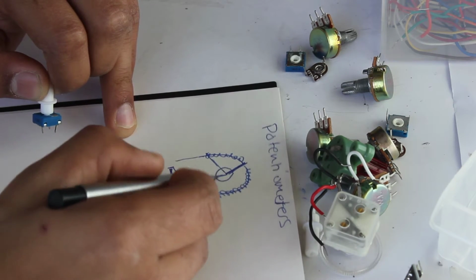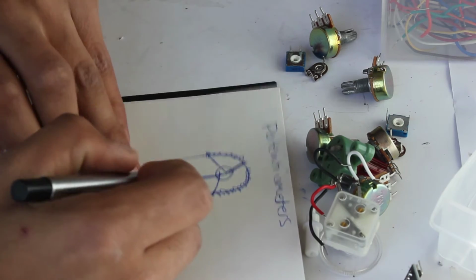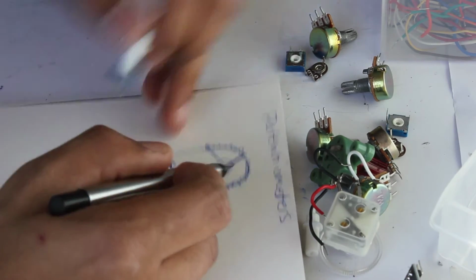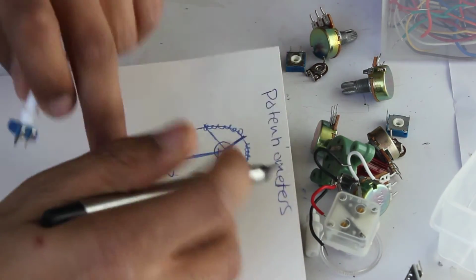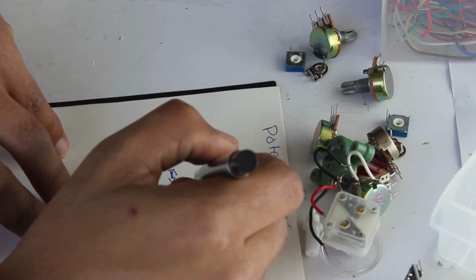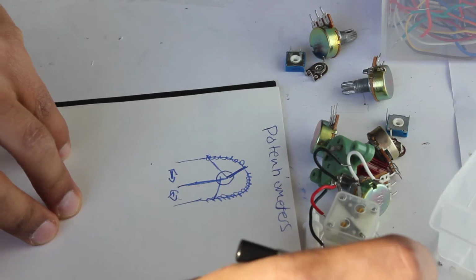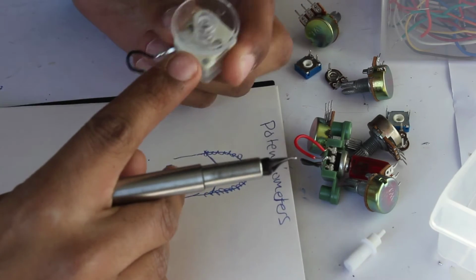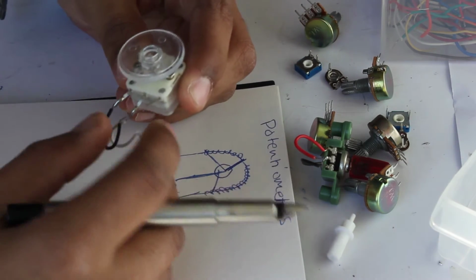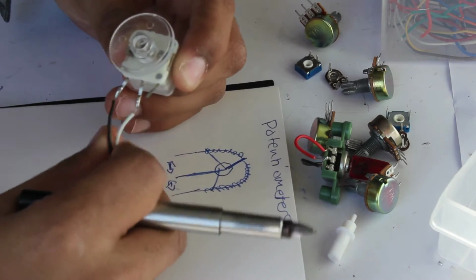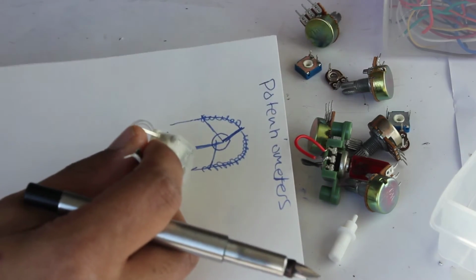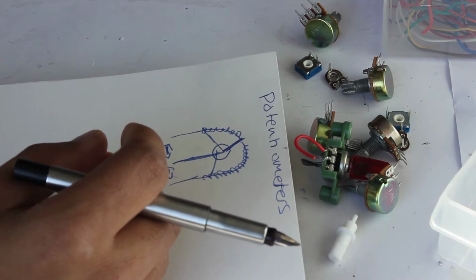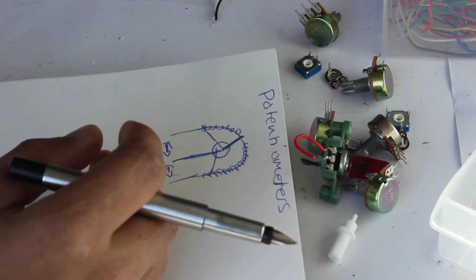Or if you spin the dial and it goes all the way around here, you have the exact opposite. You have a really low resistance in between these pins and a really high resistance in between these pins. If you put it in the middle, you can have it half-half. You can change it just by changing the angle. Why do we need that? Simply because it gives more functionality. Say I only wanted a variable resistor, so I only wanted 2 pins, and I don't really need the 3rd pin. But we can use these for both. So instead of buying some potentiometers and some variable resistors, I can buy a bunch of potentiometers and use some of them as variable resistors and some as potentiometers.